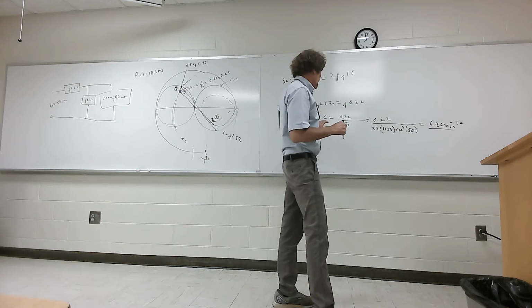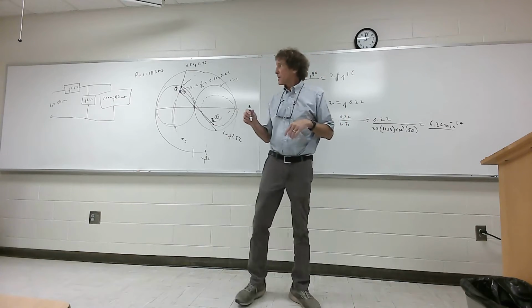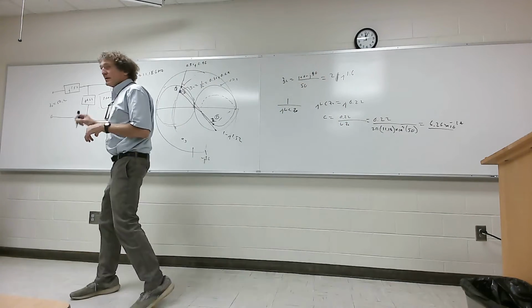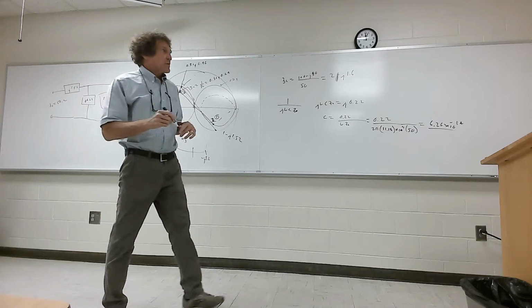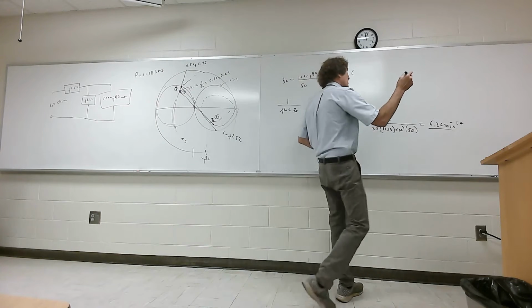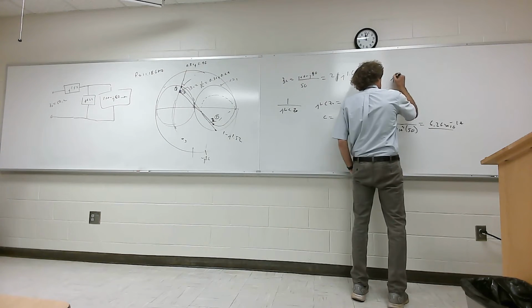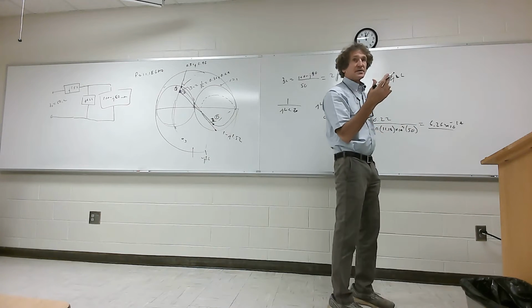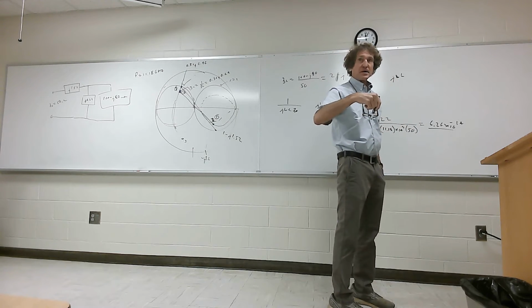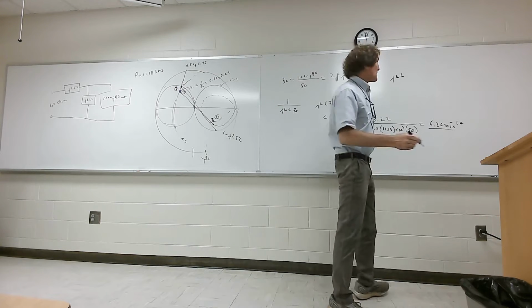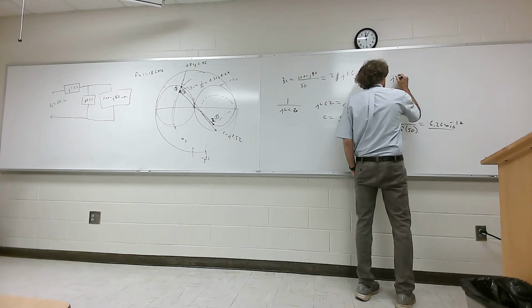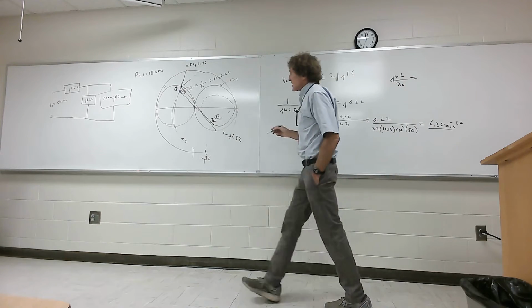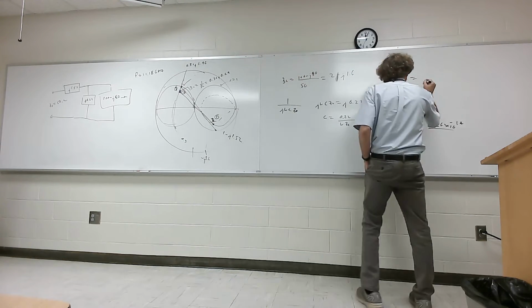Oh, okay, so now we've got to do over here, the impedance, right? It's J 1.52, it's normalized. So I start with my inductor, it's J omega L. That's an inductive reactance. If I normalize it, I divide it by Z naught. Do y'all hear me on that, everyone? So divide by Z naught. Now that's normalized, and that has to equal that, which is J 1.52.